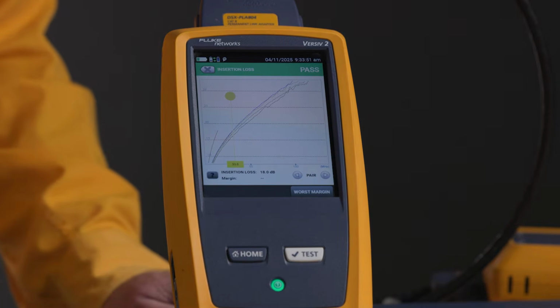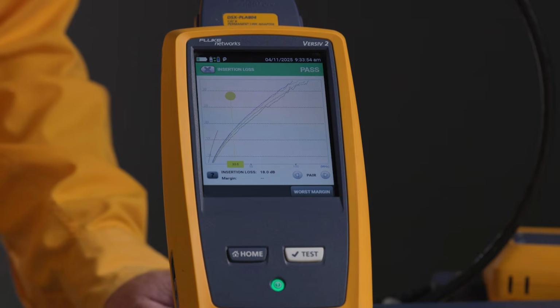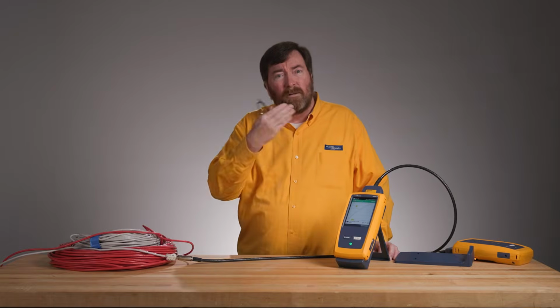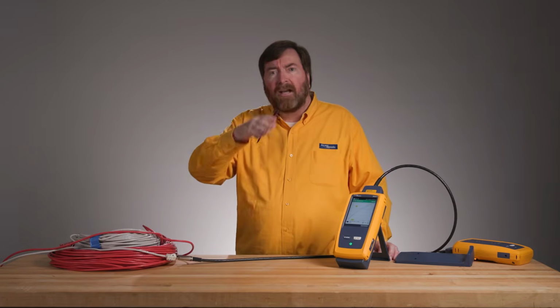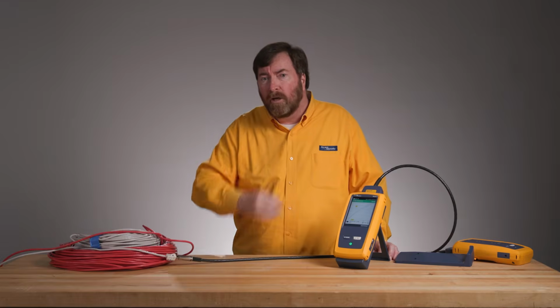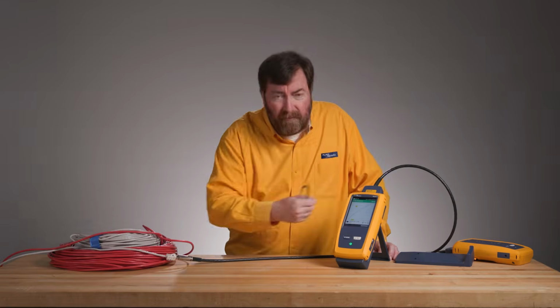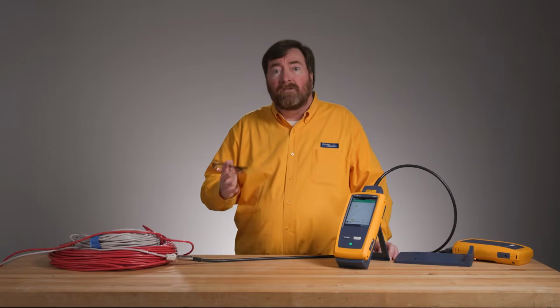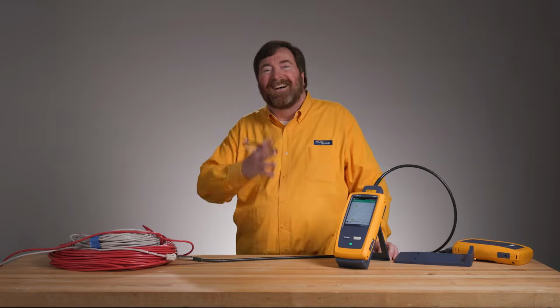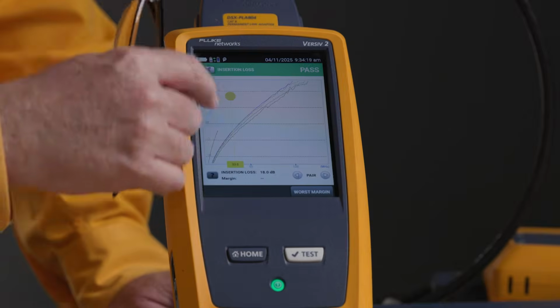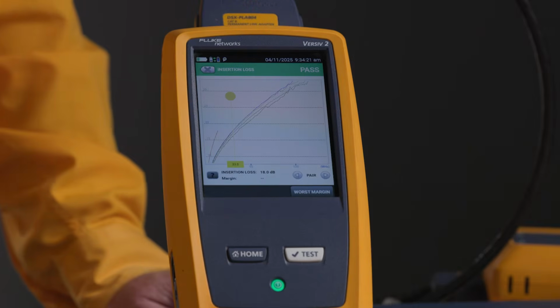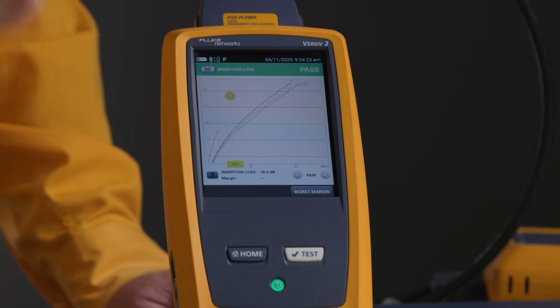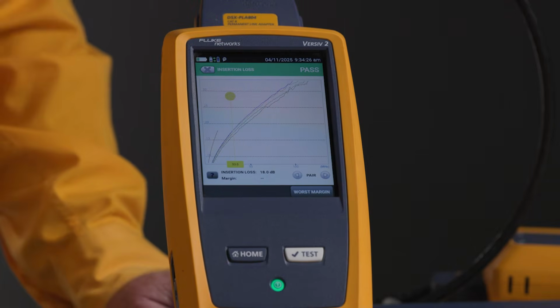So manufacturers will come to us and they will provide us with the limits for their product. And they will say, here is the formula for the curve for NEXT, for return loss. Here is the curve for insertion loss. And here's the frequency limit. We know that as the frequency goes up, we get additional return loss, but 10 megabit Ethernet does not need 500 megahertz of frequency. So they'll say, hey, here is a limit line that typically goes to a lower frequency. It's higher up, so we're able to pass the insertion loss.